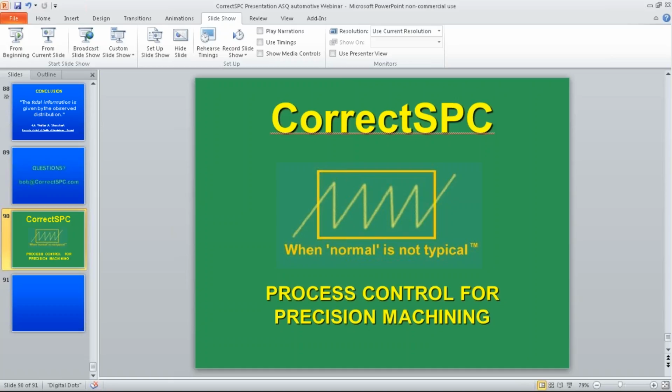Well, primarily that's all you're looking for, an adjustment, unless you have a situation where the tool breaks. That's your special cause. You have to replace the tool. I'm not one to quibble over the name. I call it control limit because those are the two limits that I'm controlling the process between. That's the A and the B. Those are the two limits that I'm adjusting between. Those are the points of control where I actually have the operator go in and react with the process.